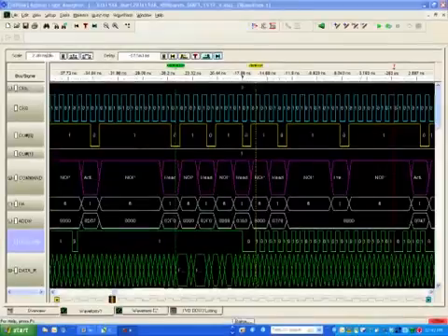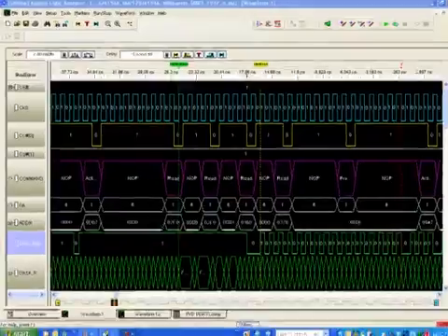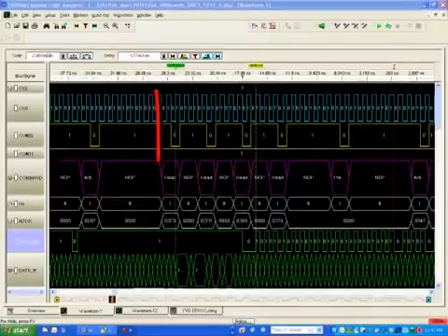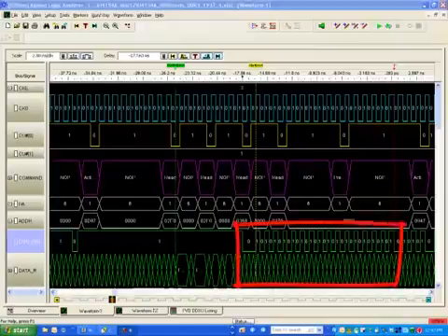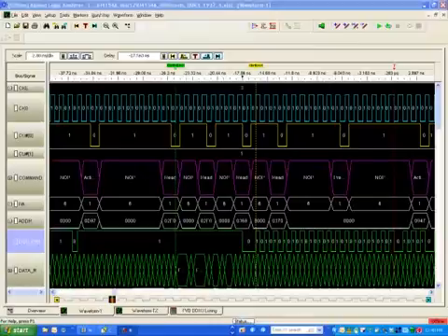Opening the state waveform, on the left we see an activate, then 4 valid read requests back to back. On the DQS line, we can see the preamble followed by the 4 back-to-back bursts of data, and we can measure the CAS latency between the first valid read request and the beginning of the data strobes. Notice that the logic analyzer triggered at the end of the fourth burst.